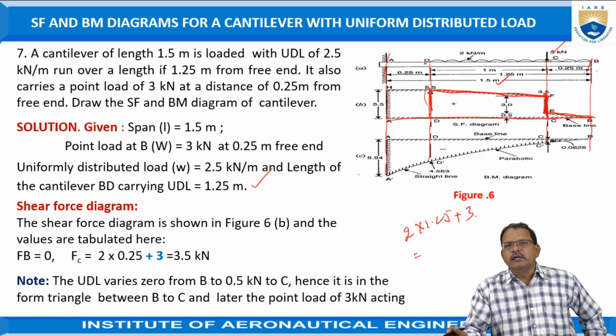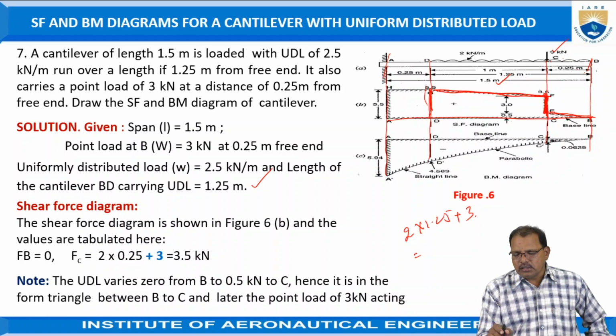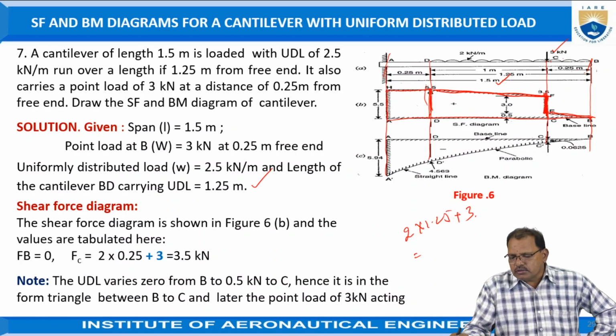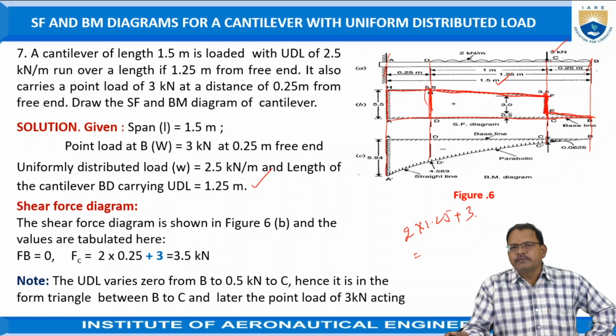Here between A and D, since there is no force acting, hence the shear force is constant, hence join horizontal lines like this. Hence this diagram is known as shear force diagram when it is subjected to point load as well as the uniformly distributed load.